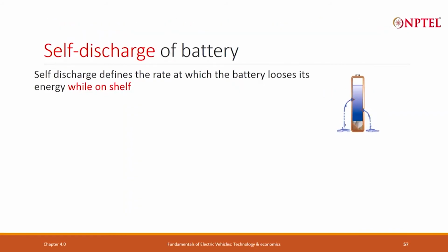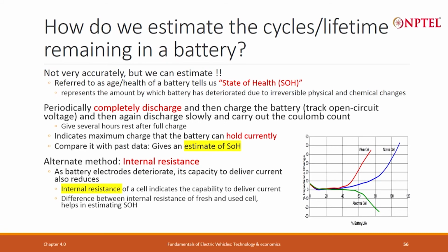So, the point that I am making is that state of health determination and state of charge determination are crucial to use in a lithium ion battery, not as important in a lead acid battery, and that is the reason you require a BMS to do that.